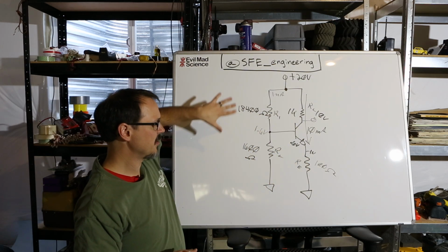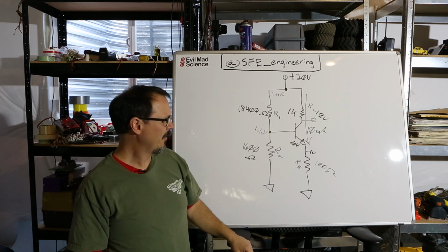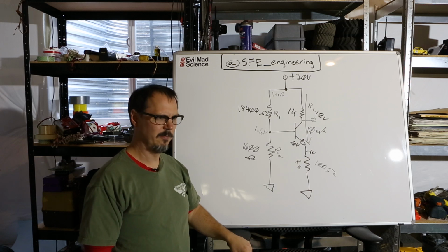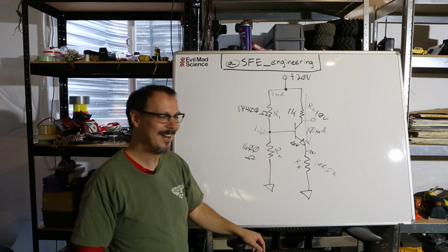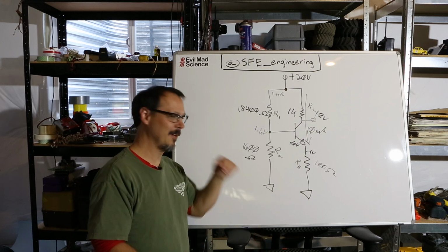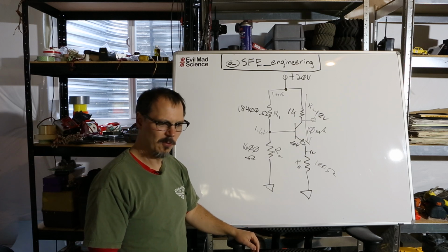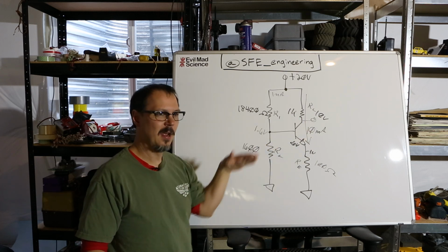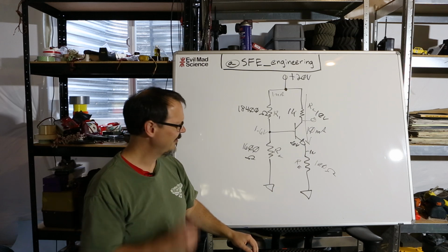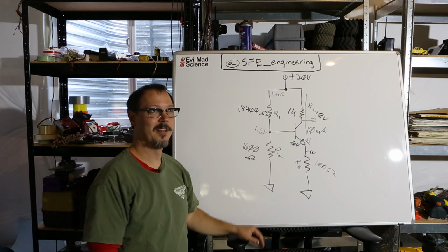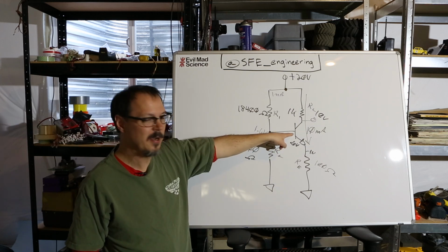When I first designed this circuit, I had it in my head like, I want to run this thing, man. I want to see if I can push some real current with it. So I had my quiescent current set to 50 milliamps, right? Well, I set up the circuit and everything was off, of course. Interesting thing was I had a voltmeter on this and the bias point kept changing as time went on, like a few seconds. It would get like, what's going on there? Why is this changing? Oh, and as I was sitting there, something's burning.